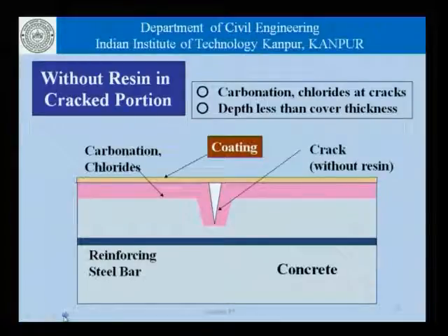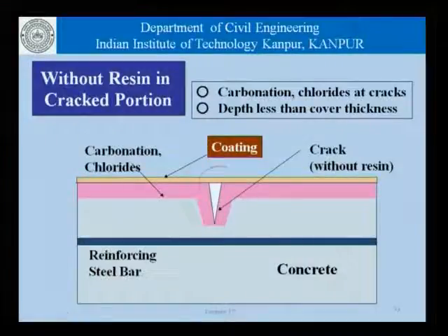In the case when we are not trying to do impregnation of cracks, we said that in certain cases when the cracks are not very deep, we may not like to do impregnation specifically and only just do the surface coating. Now, if we do only the surface coating, what we should remember is what is happening here. Because of this width of the crack, this coating must have enough deformability to remain as an intact cover over the crack and prevent material from going inside, and that is what it is designed for, even when the structure is under load.